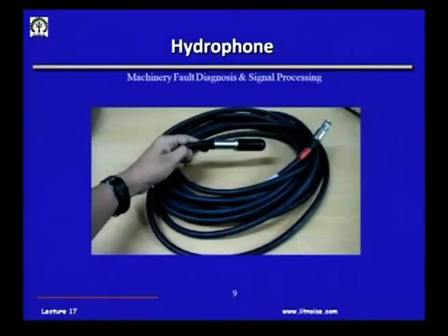Now, these microphones could be used to measure noise underwater, and these are actually known as hydrophones. The piezoelectric sensing element is here, and this black one is just a protective cover. When the water waves come and impinge on this surface, the piezoelectric crystal inside also gets a motion, and this signal is converted and sent to a charge amplifier. You will be wondering why such a long cable; this is about a 10 meter long cable. This could be ordered even up to 1000 meters, 1 kilometer.